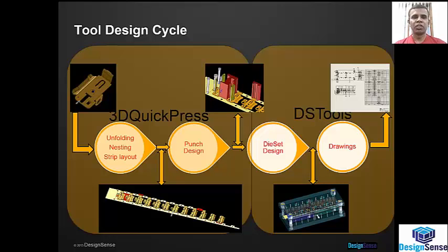well-designed die set. So with DSTools, we take away both these complexities by providing easy choices to the user, as well as making use of the choices to generate the die sets and make decisions on the standard parts, as well as the required die set sizes. And from this designed die set, the bill of material as well as the drawings are generated automatically. Now, with this, let me go to the demo.